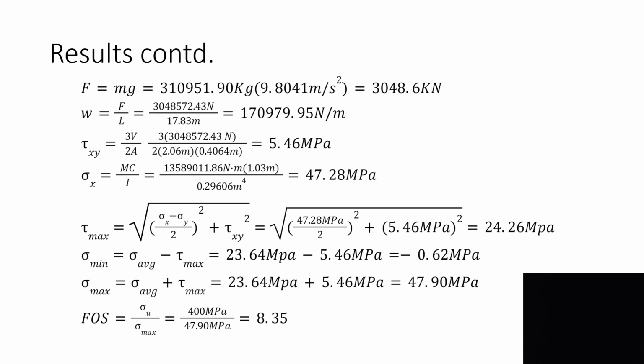The minimum normal stress was 0.62 megapascals in compression, and the maximum was 47.90 megapascals in tension. The factor of safety that we calculated was 8.35 times the recommended load.